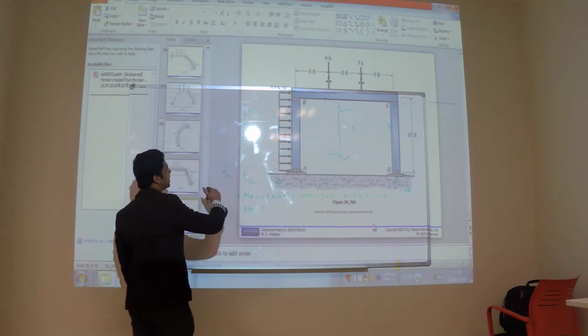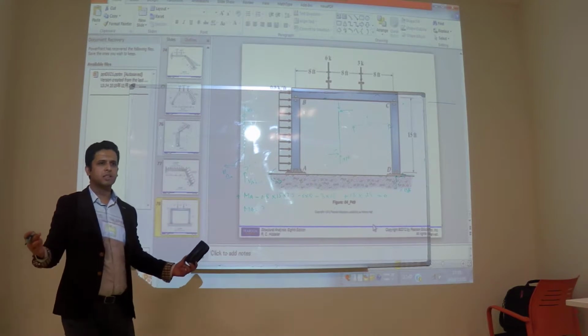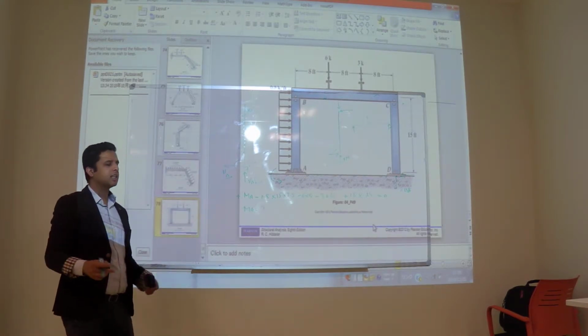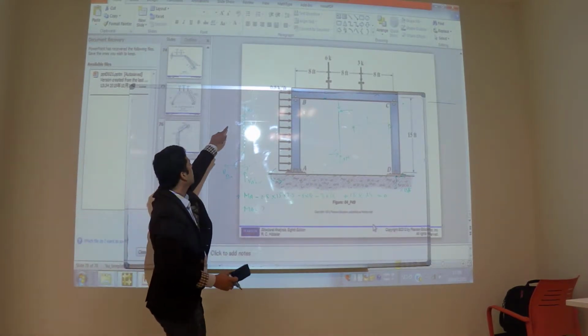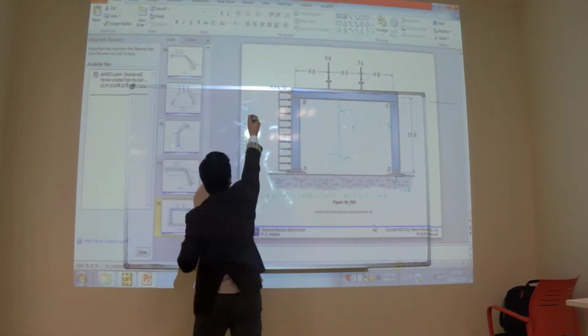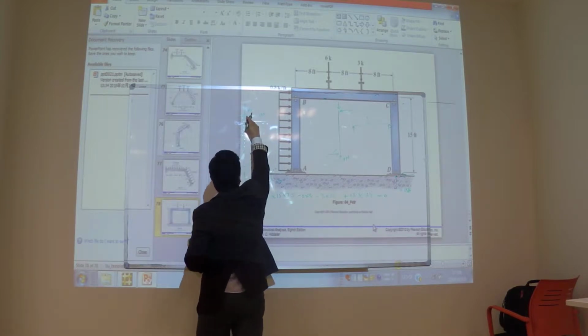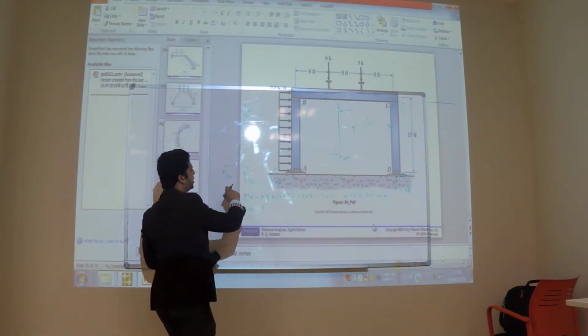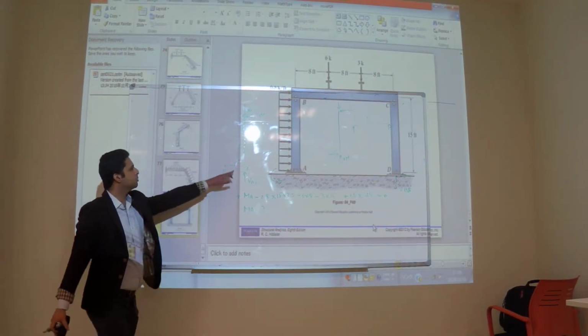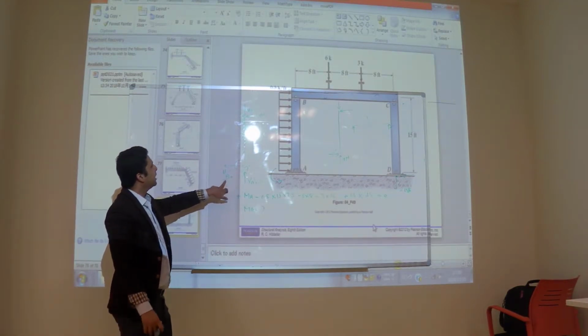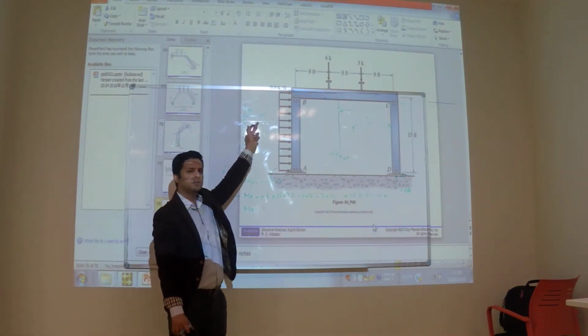Only HA is unknown, and now you can apply sigma fx, or because there is one more here, I think it is HB. So you can take a moment here, you will get HA, because you know this moment, and once you have HA, you can apply sigma fx, you can get HB.